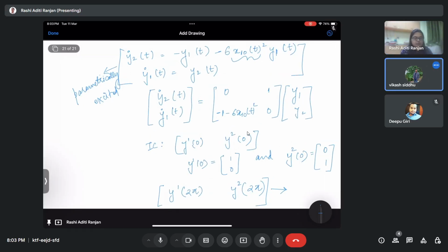Madam, I have a doubt. In the resonance condition, principal parametric resonance condition and combination parametric resonance condition, is it necessary that omega is exactly equal to 2 times omega n or 3 omega, or can we say it is approximately equal to? Yes, definitely it is approximately equal. Exactly equal is not possible in the case of a practical system, because there is definitely some variation.